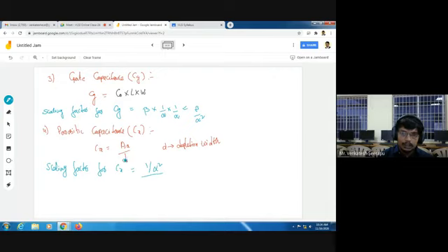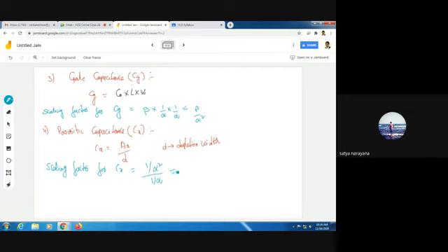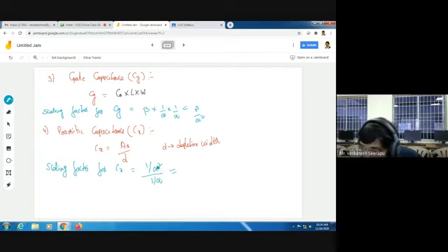It is a small d which is a depletion width, and it is having a scaling factor 1 by alpha only. Capital D and voltages alone have the scaling factor 1 by beta. For all the remaining ones, the scaling factor is 1 by alpha only. So 1 by alpha square by 1 by alpha is the same as 1 by alpha. Yes, the scaling factor for parasitic capacitance is 1 by alpha.